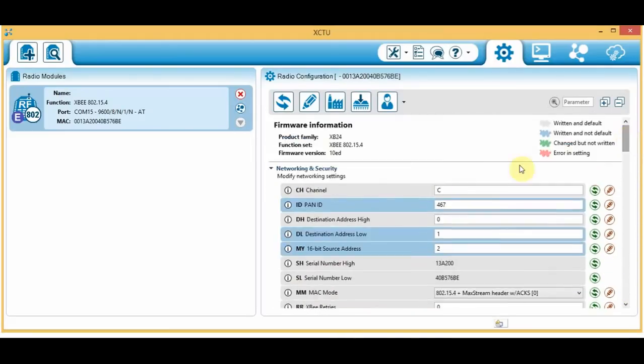These are the ones that you change when you're using your XBee module in different modes and for different applications. So up here on the settings, there are several icons. There's a read icon, which reads all the radio settings that are saved on your XBee module, and there's a write icon, which saves any changes that you've made to the configurations.